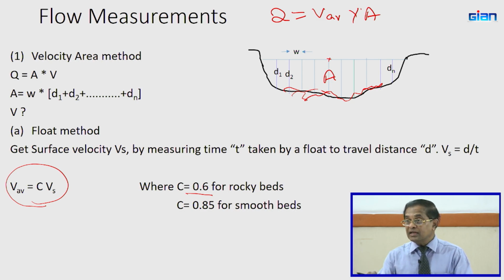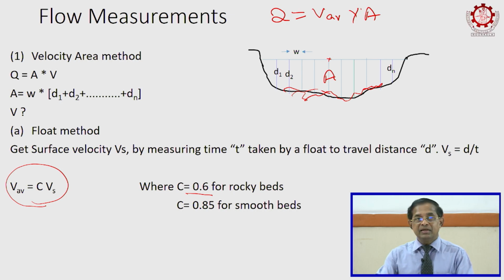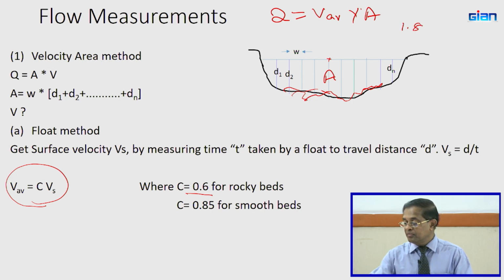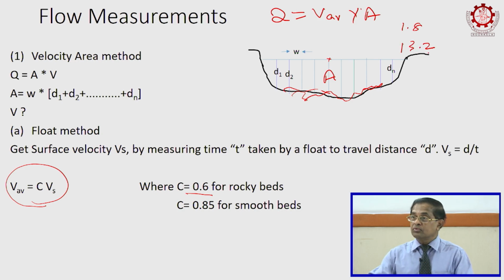Now you refer that to the hydrologist's data set, since you know the date, and see whether it is in the range; it will not be exactly matching. If the hydrologist has said it will be 1.8, and you get even 3.2, you are in the same range, but if you get 13.2, then there is something wrong.